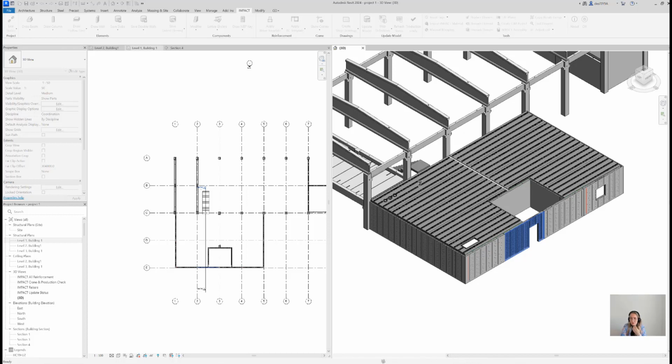So a double wall shop drawing is being created, and once you create the shop drawing, Impact will also pop up with a suggestion to open it. Each shop drawing that is created is actually part of an assembly view. I'm going to scroll up and down in the project browser when Impact is ready and show you where to find the shop drawings in Impact Revit.